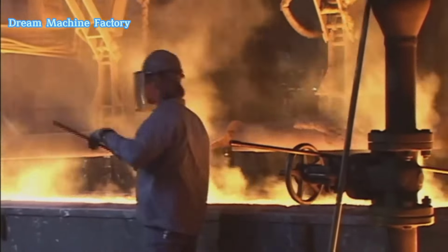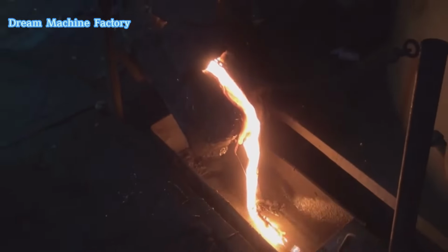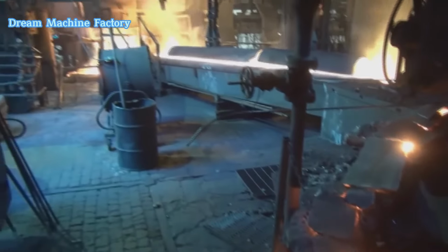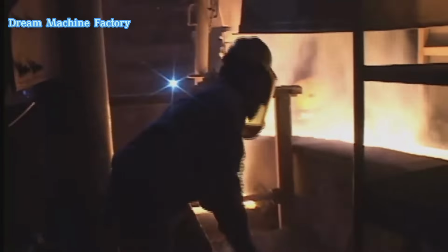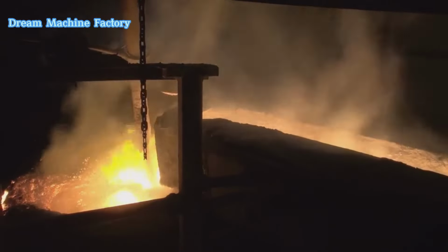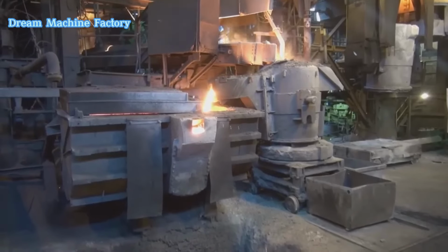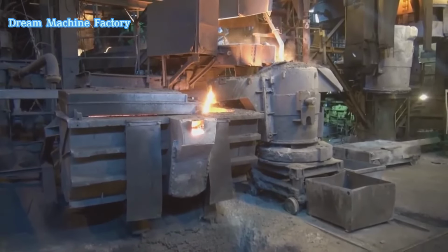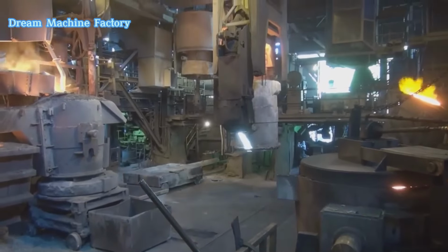The addition of limestone aids in the removal of impurities by forming slag, which rises to the surface and is skimmed off. To maintain the high temperatures necessary for efficient melting, hot preheated air is continuously blown into the coke bed through two air inlets at the base of the cupola. As the metal melts, it picks up carbon and sulfur from the coke before exiting the furnace through the tap hole.